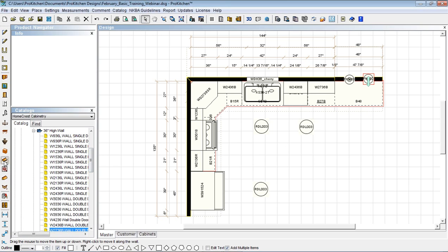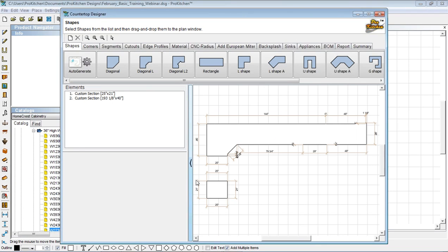How do I get that? I'm going to click on the little icon that looks like a Harry Potter wand, and it automatically imports the pieces that I already created, and it gives me a choice to create a new piece and to choose a shape. I'll grab a rectangle. That's 48 inches here, so to give it a 15-inch overhang, I'll make it 63. And I had it 4.5 thick, so it'll need to be 16.5 to give it the overhang I want.